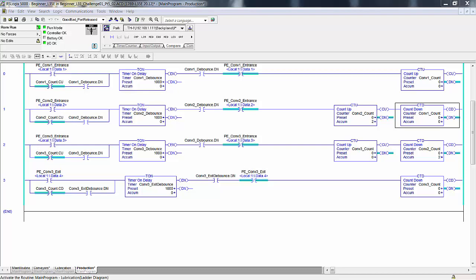In our images on the page before last, on those diagrams, you would have to increase it so you would never really have two at rest on the conveyor at a time. You'd have to space them out and say the conveyor is full when it's two. The preset for the counter has to be set for the longest carton. And that's what basically the solution I just said. The preset for the counter would have to be adjusted for each type of carton to avoid losing valuable buffering space. With all this in mind, let's do something simple.